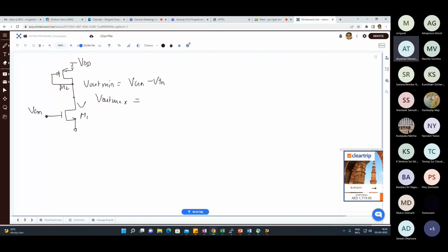Here the gate and drain are short circuited, right? So it will always be in saturation. So if VDD is 1.8 volt, VT is 0.4 volt, and this signal goes to 1.9 volt, it will work. The gate is at 1.9, and the source is at 1.8, so you need to keep it so. If it goes to the subthreshold region, then it will turn off and enter the subthreshold region. There the current equation is different, and the GM equation is different.